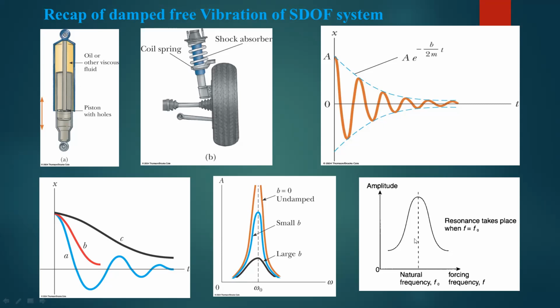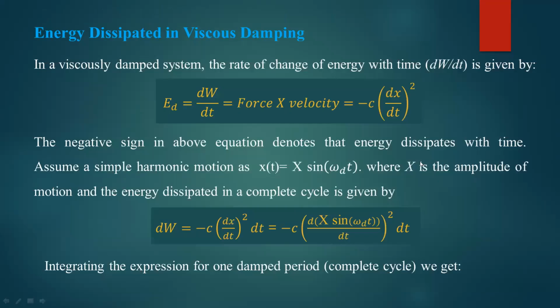This dotted line condition represents the occurrence of resonance because of the coincidence of the natural frequency with the forcing frequency. The natural frequency is the frequency of the material itself, that is radical of K over M, but the forcing frequency is the externally exciting frequency. So these should never coincide. That is the method by which we can design our system.